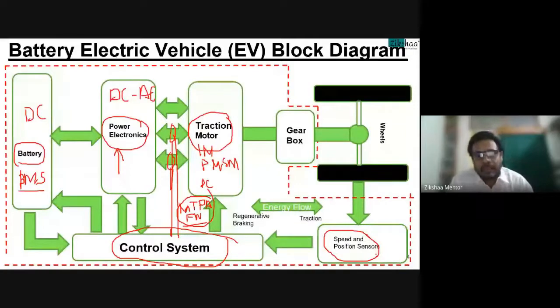So we are looking into sensorless controls, something which has been around but wasn't used that much. DTC, called direct torque control, is inherently sensorless. We are also looking into actual sensorless controls, so that we only measure our currents, and that would be enough to control our motor.